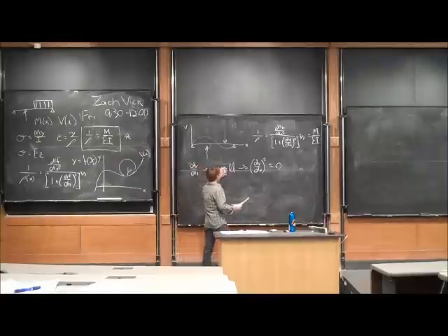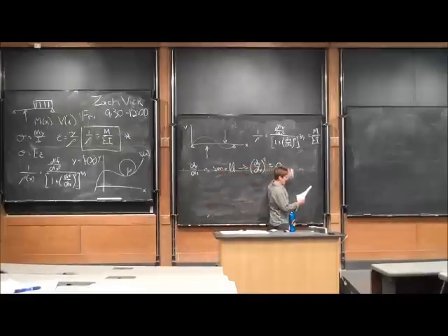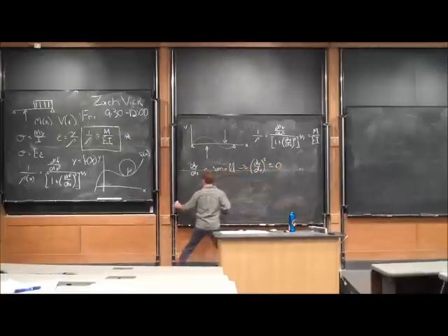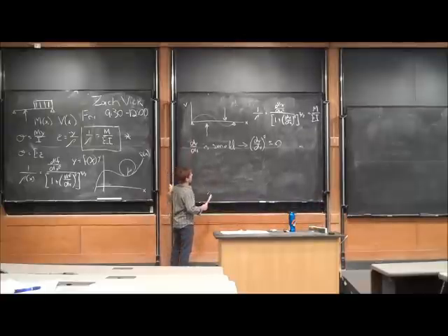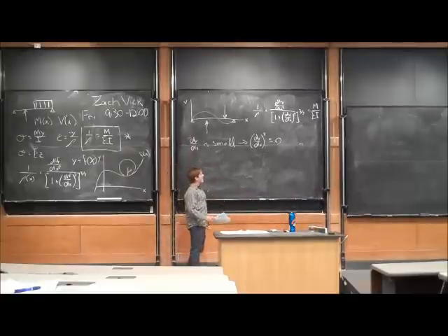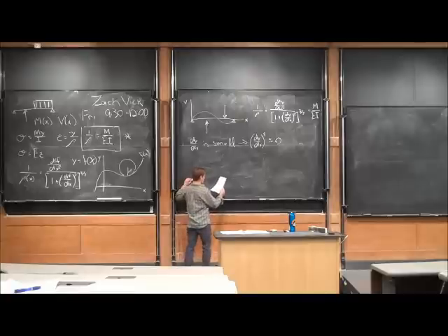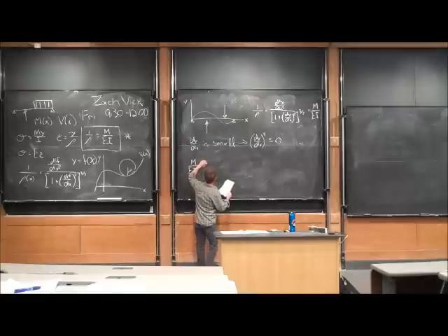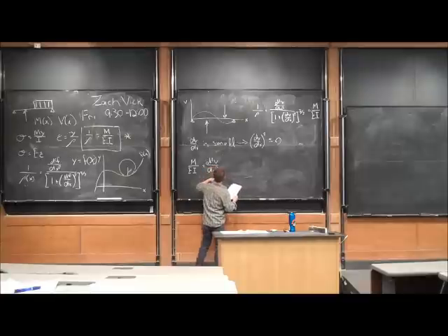So this equation greatly simplifies down to the fact that now we can relate the moment to the deflection by just one second derivative. So now we can see that the moment at a given location in x is equal to EI d squared v/dx squared.